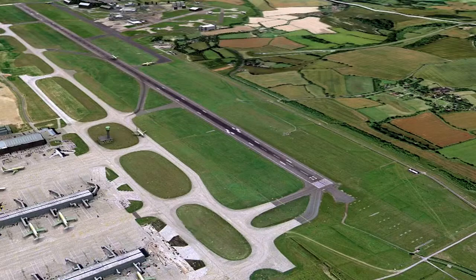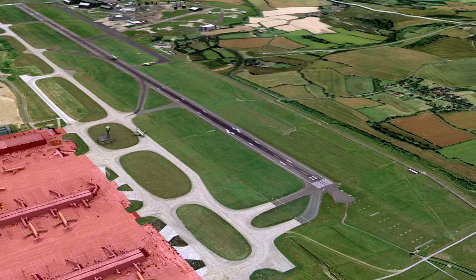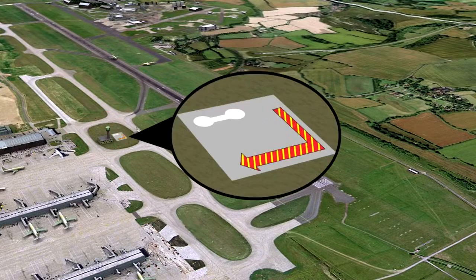Certified aerodromes complying with the Annex will, in addition to having all the specified facilities, such as ground marking and aircraft handling, also have an aircraft movement area, a manoeuvring area, and an apron. At controlled aerodromes, there will be a control tower with a visual room. If an aerodrome accepts non-radio traffic, then it must also have a signals area laid out that is visible from the air within a defined distance and height from the aerodrome. We explain these signals later on.